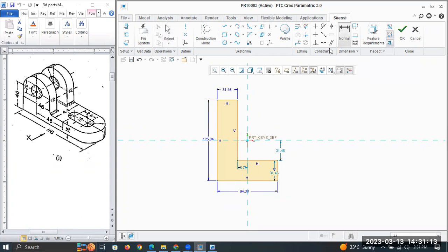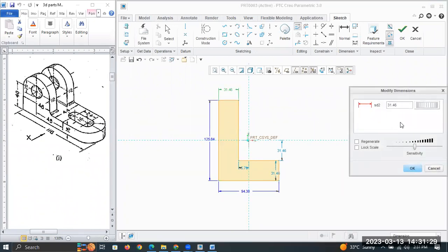Now I think the complete height you are supposed to enter from this to this. So I am selecting this modify command and I am going to select the dimensions one by one. What is this value? What is this value? 48. This wedge thickness. It is highlighted, no? 48. Then this value, total height: 40 plus 24. 40, and the diameter is 48. Half of that. That is what I am saying. 40 from the center to the base, it is 40. Then this becomes the radius of this diameter. Okay, so which means 48 by 2 is nothing but 24. So you should enter 64.